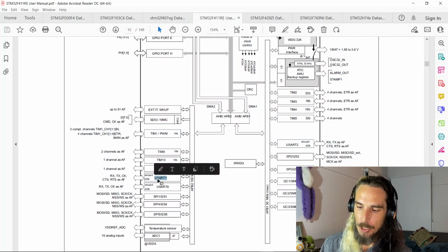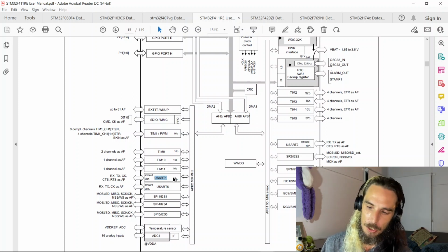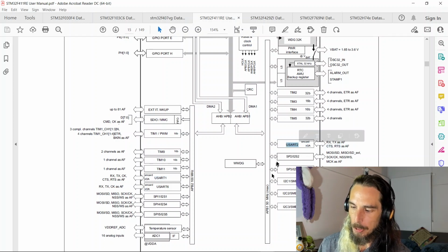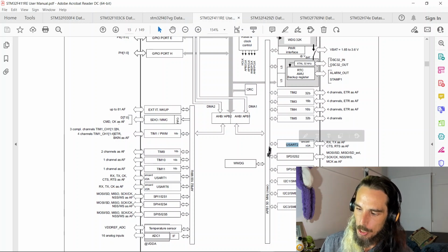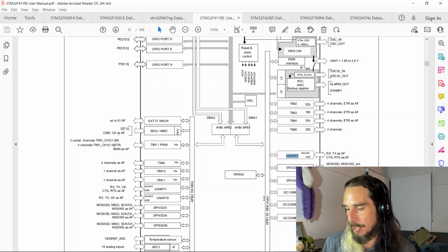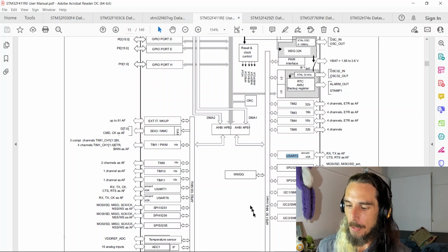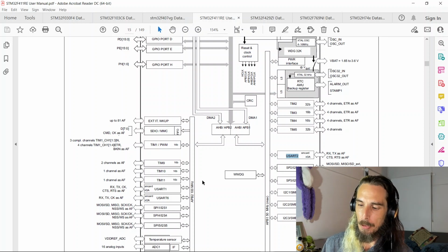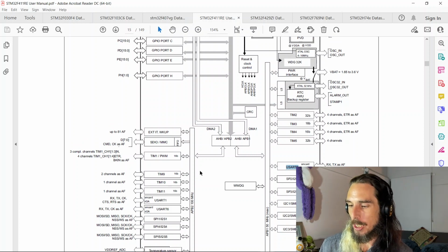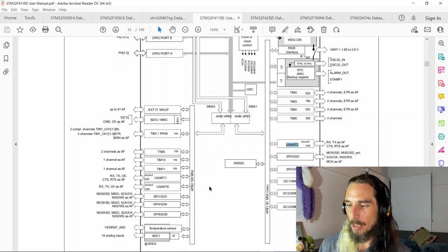So for example, if we were using the USART1 peripheral and we were obtaining its clock directly from the bus, it's going to be receiving a 100 megahertz clock. Whereas if we were using USART2, which is connected to APB1, then in the case where it's getting its clock from the bus, it's going to be receiving a 50 megahertz clock if those buses are running at their maximums. And those buses don't necessarily have to be run at their maximum, depending on how you configure the clocks, and the various prescalers and things like that will determine what those clock rates will be on the buses.